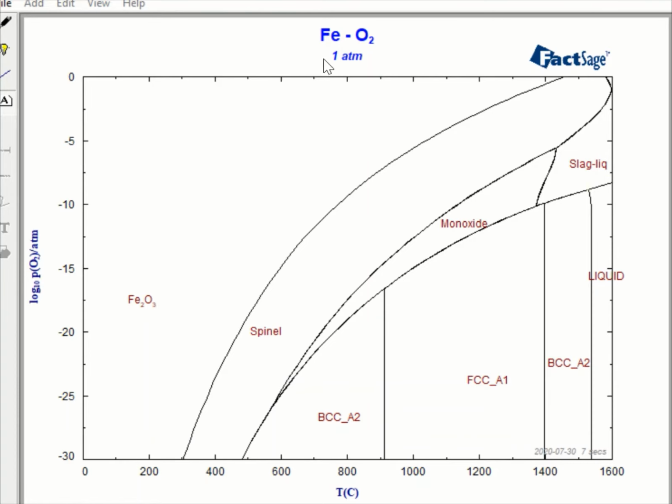So when you put the iron at different temperatures and different partial pressures, this kind of oxidation or reduction can happen depending on the partial pressure. Okay, so this is the boundary at the given temperature. So at 800 degrees Celsius, if you're higher than this one, you start forming iron oxide FeO from the pure iron metal. So that's what it means.